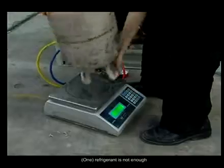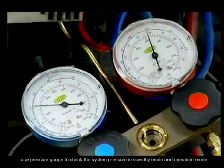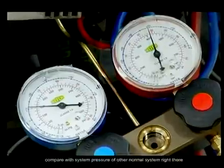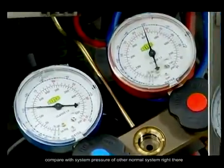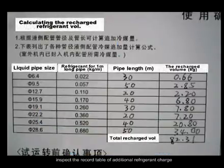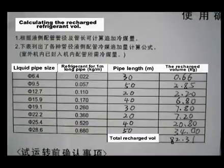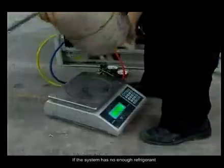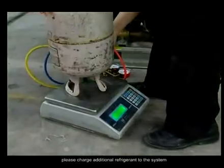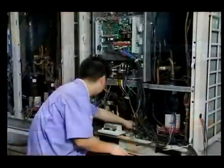1. Refrigerant is not enough. Use a pressure gauge to check the system pressure in standby mode and operation mode. Compare with the system pressure of another normal system nearby. Inspect the record table of additional refrigerant charge. Then judge if the additional refrigerant is too little or the system has a leakage. If the system does not have enough refrigerant, please charge additional refrigerant to the system and find out the root cause of why the refrigerant is not enough.